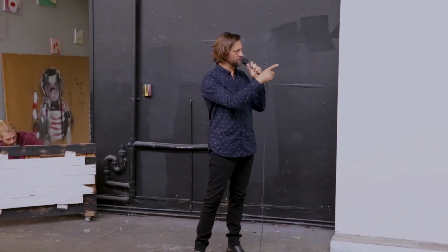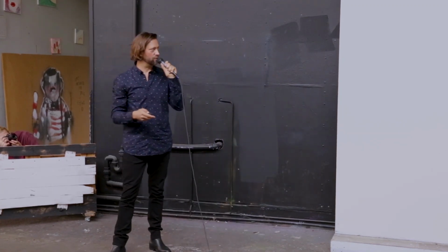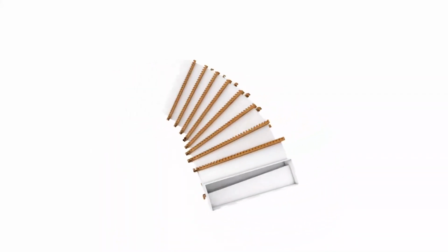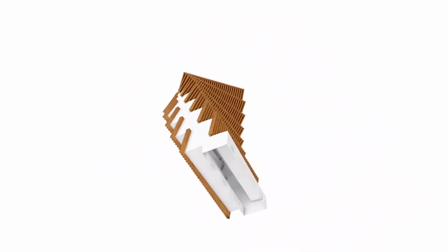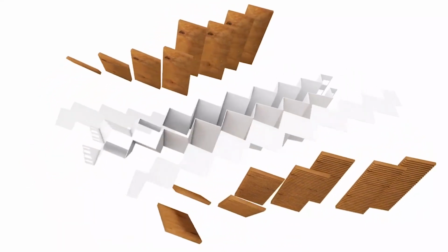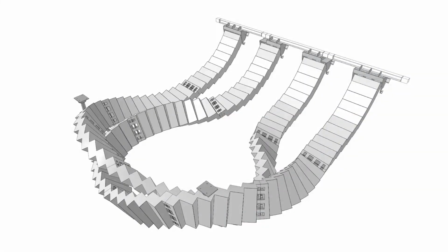There's no way this project would have been able to be installed in that sort of rapid time. So we had to rethink how we were designing it really from the ground up. So we looked at another structure, which was essentially an aluminium box section that the treads would then get attached to. So this structure then became the basis of how we were going to build it. That essentially no longer was there a central pipe. We looked at an accordion aluminium structure that was prefabricated into these separate elements. And then that would all get bolted together on site.